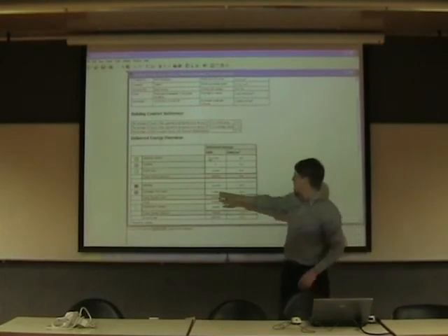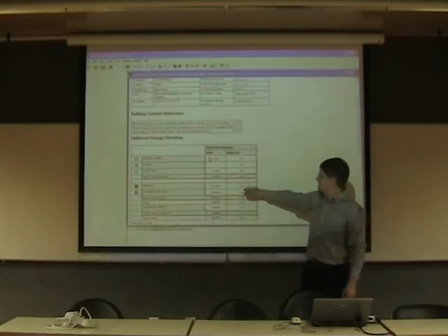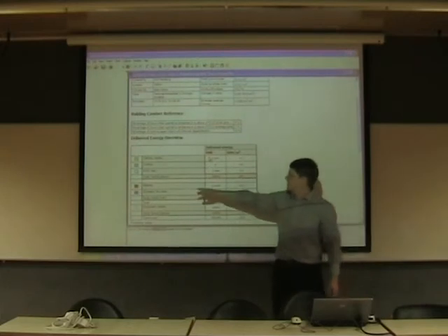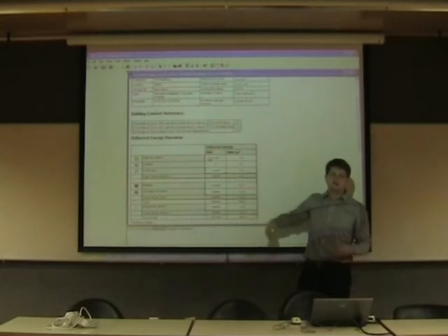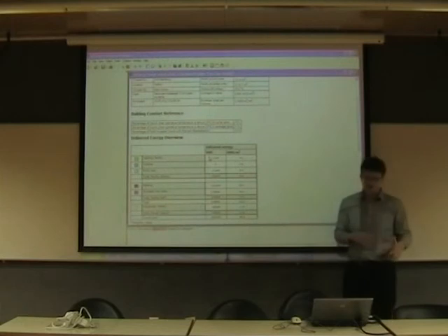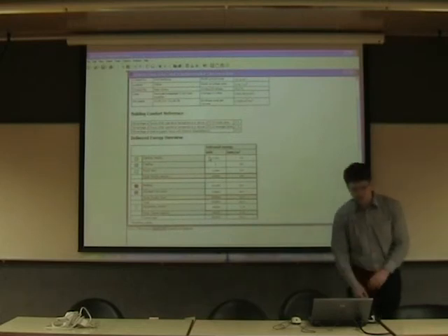Don't zoom it. But this heating energy consumption per heating area is 40 in this case. And as I said, I haven't put in any cooling energy, because I wanted to see which kind of situation we get when I don't put in any cooling devices.